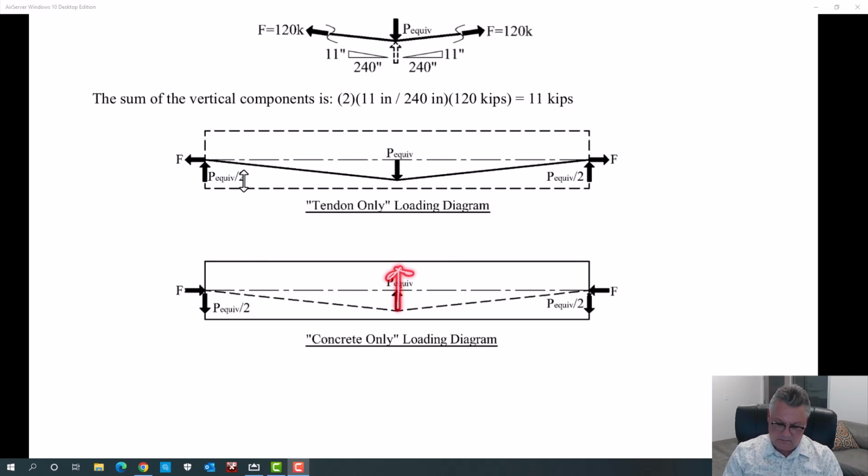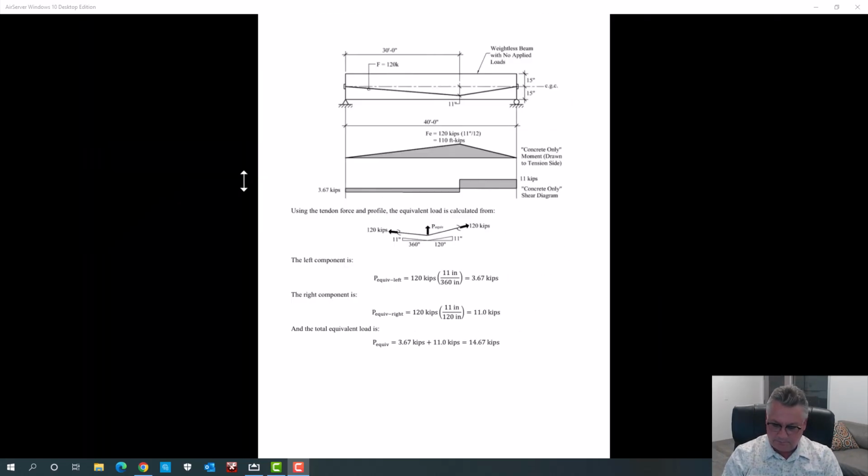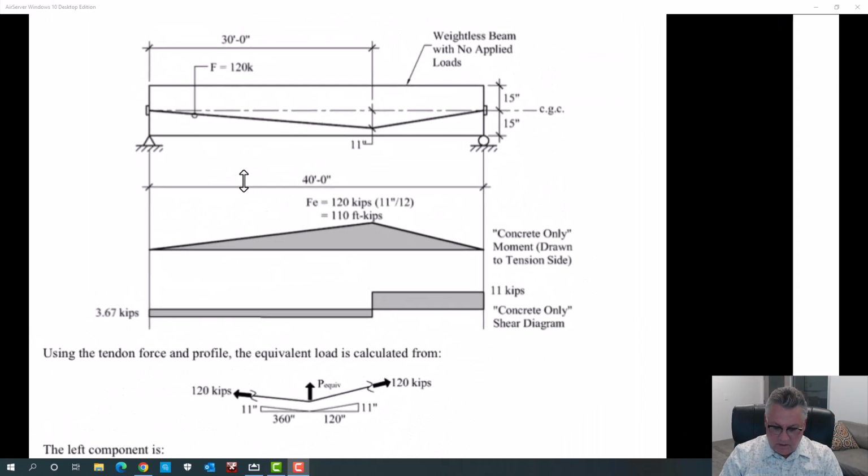And in most of pre-stressed concrete, and really all of post-tension concrete, we're also trying to lift the beam. We're also trying to counteract gravity or the loads that are being placed on the beam. That's the only time pre-stressed concrete makes sense, is if we are counteracting what gravity is doing. If we were doing it in the same direction, it probably wouldn't be nearly as successful. But we can counteract gravity.